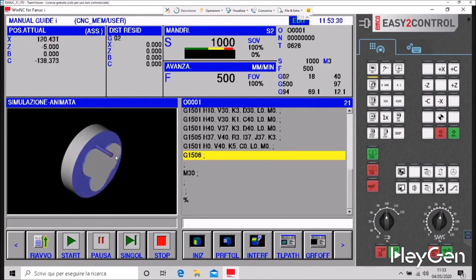Okay, now it seems like we're doing something bad, but in the end, T will come out. Next time, let's choose another letter. First pass at a depth of 5 mm, second pass, another 5 mm, so let's remember that when we draw a free shape, both C and X are the coordinates of the actual distance from the center of the piece, so basically radial dimensions. Let's remember that the shape needs to be closed.